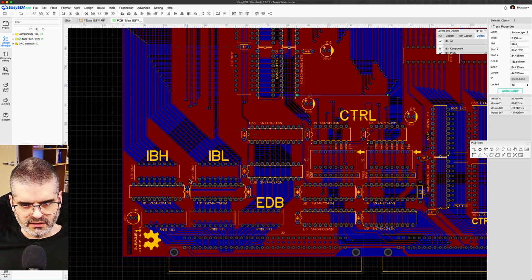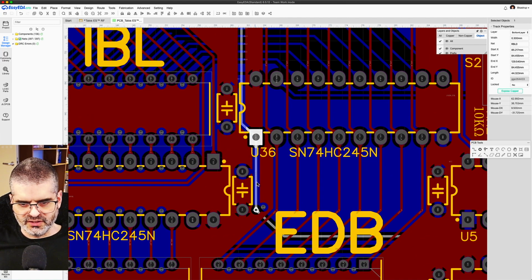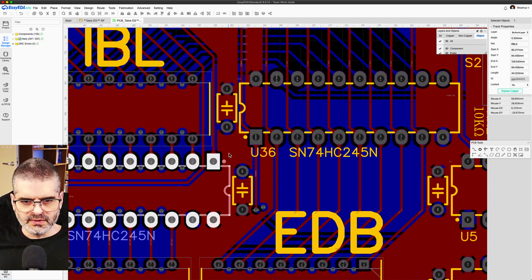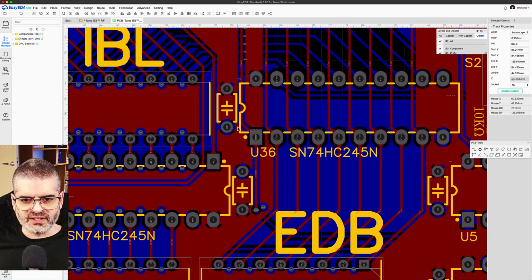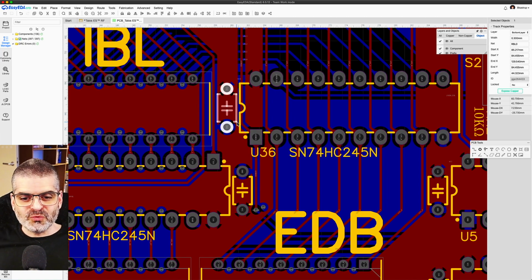So let's go down. Let's go to this side instead. Okay, it comes here. Oh, here's a dead end. Let's zoom in. Here's a dead end because there's a signal line here preventing the copper fill from going further. So you have to go up, go up, go up, go up. Oh, it's not a dead end, but look how thin this is. If all the power for this entire part of the circuit is coming through this thin little line, we have a problem, Houston.